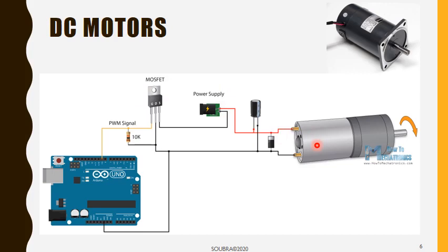Without getting into too much detail, the kickback of the motor is the phenomenon that happens whenever you apply a voltage to the motor and then stop it: it keeps on rotating, generating its own voltage. So in order to secure the system against the injection of that generated voltage, the diode prevents the kickback of the motor's voltage back into the system.